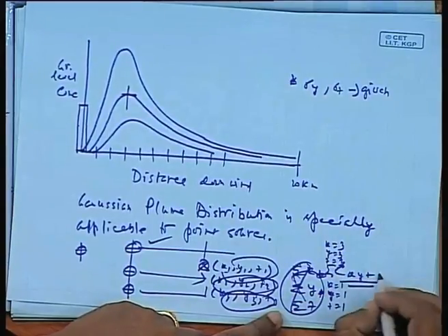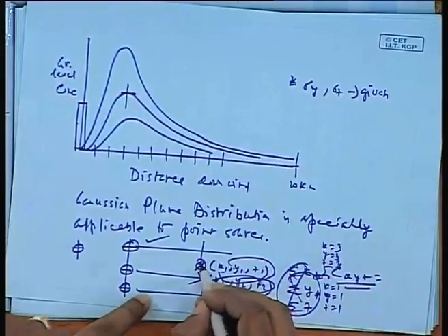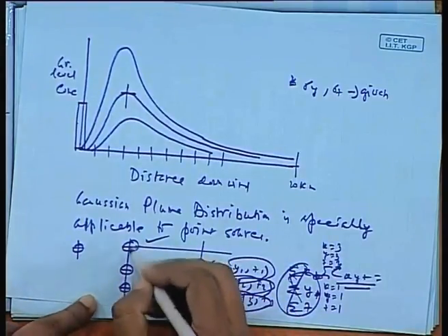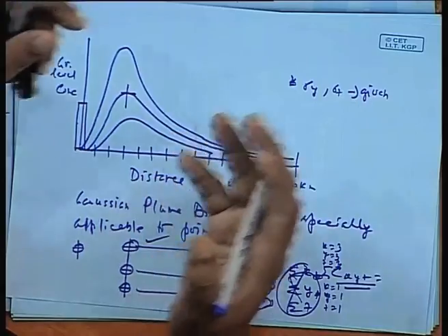So we can find out the concentration at this point due to the contribution of the line sources. So point sources can be used as line sources. So the Gaussian plume distribution is essentially worked out for all these kinds of problems, and is quite applicable and preferably used. Okay, we complete today's lecture here.